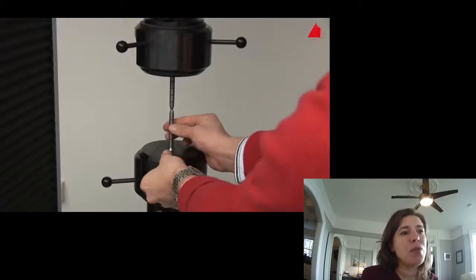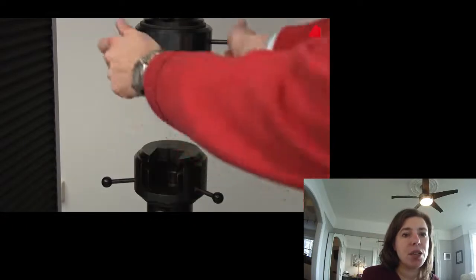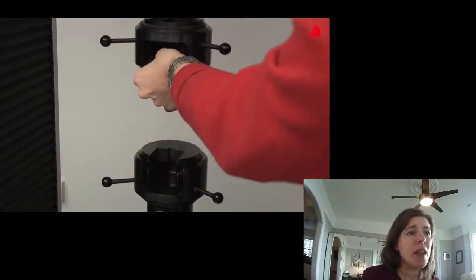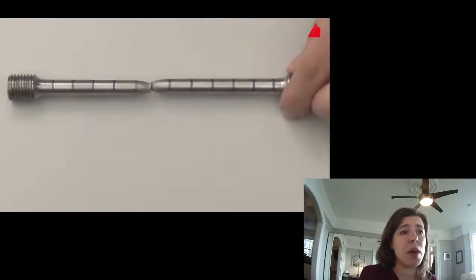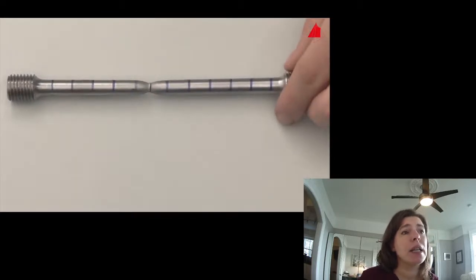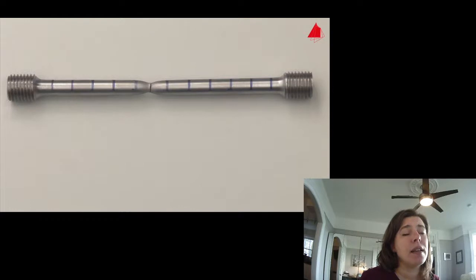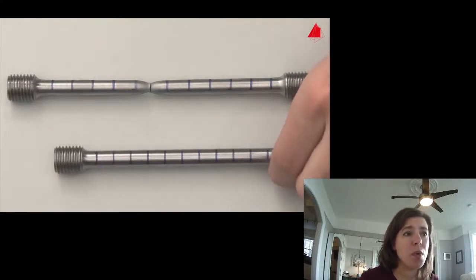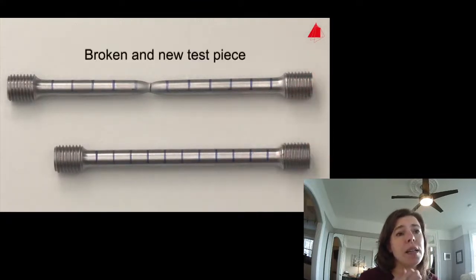So you guys remember those failed pieces of steel that I showed you in the first lecture of Structures 1 on the Structures 2 work table? He puts the fragments back together again. With the help of the distance marks, the percentage elongation after fracture can be determined. How much is deformed? If they put the original marks together, the permanent strain after fracture here amounts to about 30% in this example.